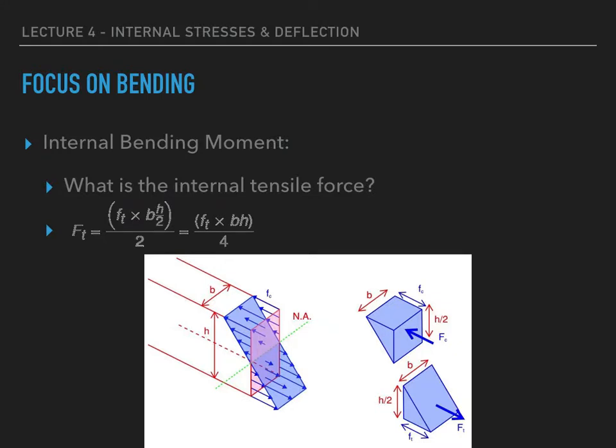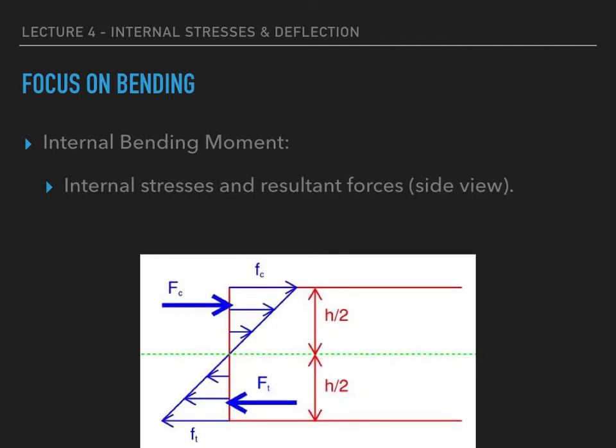If I do the same thing on the bottom, the tension wedge, you can see that we get exactly the same answer but with an Ft instead of an Fc. So again, nothing crazy there, but we end up with equivalent concentrated load Fc and equivalent concentrated load Ft. Go ahead and locate those concentrated loads where they would be for a triangular uniform load. We know that that's 1/3 from the larger end, so 1/3 from the top or the bottom respectively, and I put them something like that.